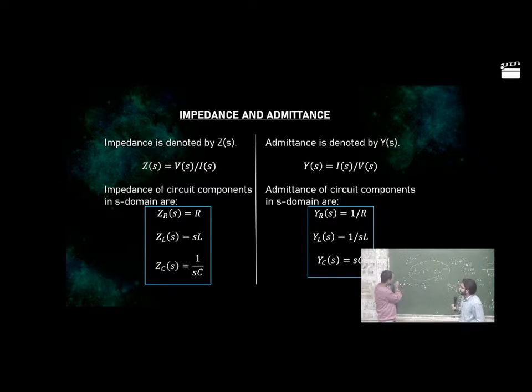If we are considering a resistor, then there is no angle in the resistor part, only real part. So there is no S term there, right? But for inductor and capacitor, we have 90-degree lead and 90-degree lag. So for capacitor, we write 1 by SC, this is providing minus 90 degree, and for inductor SL, this is providing plus 90 degree. That's the reason why we are taking this, provided that we have no resistive components associated, like it's a pure inductor or pure capacitor.